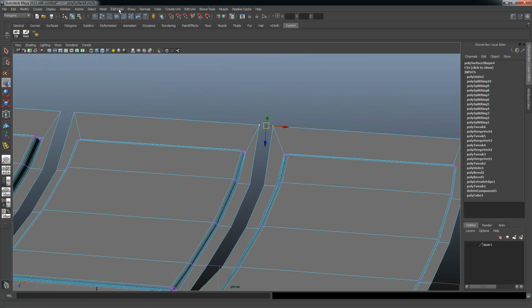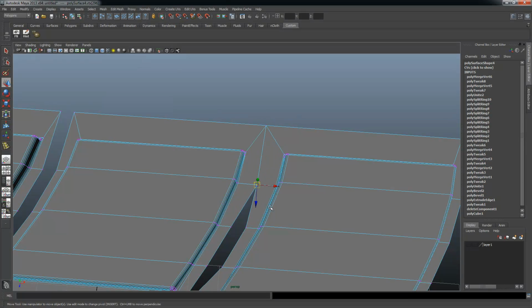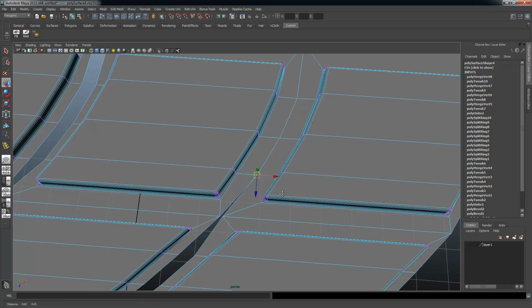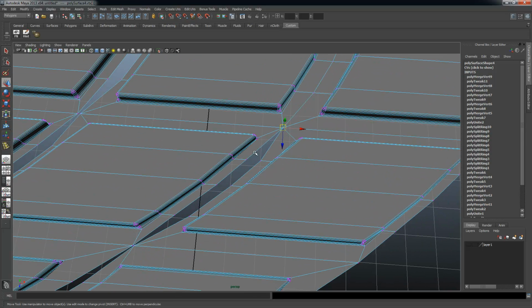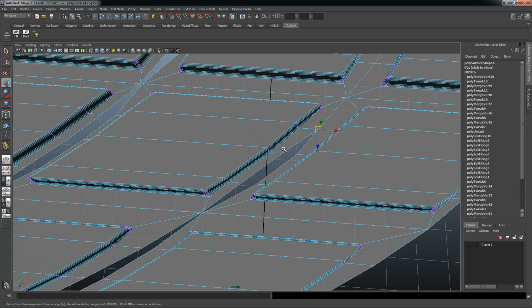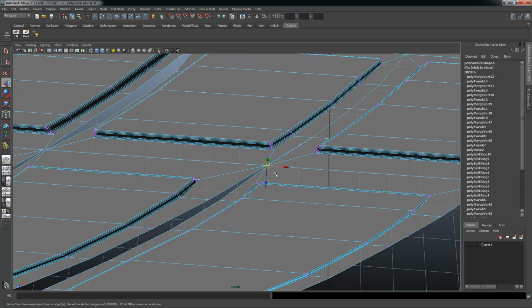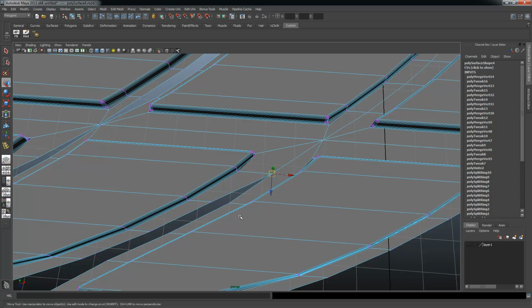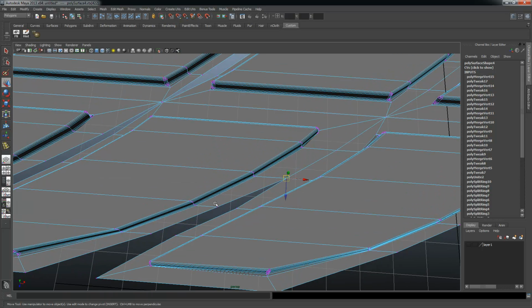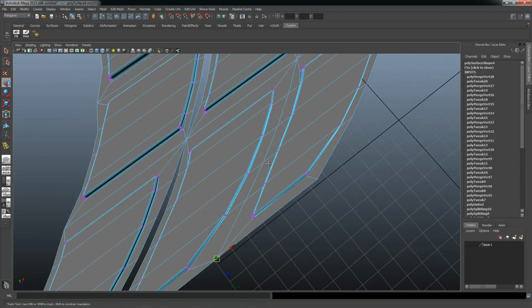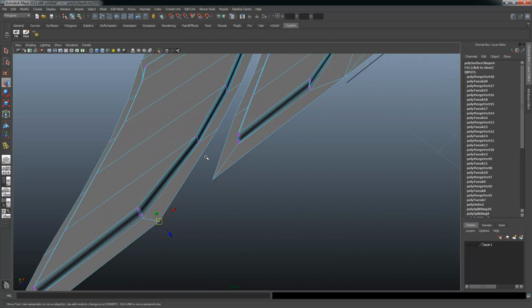these vertices, say Edit Mesh, Merge to Center, and it's going to split the difference between the distances perfectly. And what that's going to do is actually find that center line that I could have spent hours trying to find by sitting there and moving points around until I got all these to line up. Or I can just come in here, merge these guys, merge to center on all the vertices on both sides of the scene. And this will work with a pattern that is even much more complicated than this one.